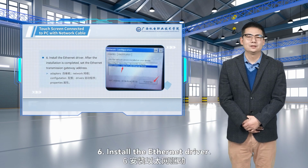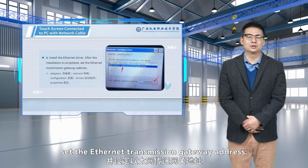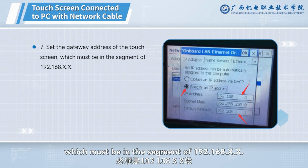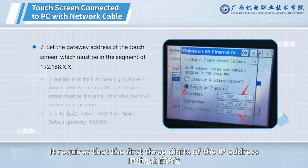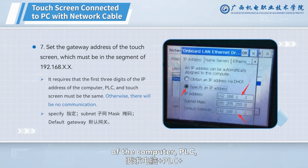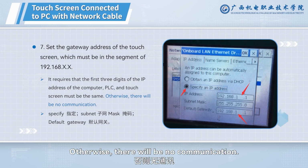6. Install the Ethernet driver. After the installation is completed, set the Ethernet transmission gateway address. 7. Set the gateway address of the touchscreen, which must be in the segment of 192.168.x.x. It requires that the first 3 digits of the IP address of the computer, PLC, and touchscreen must be the same. Otherwise, there will be no communication.